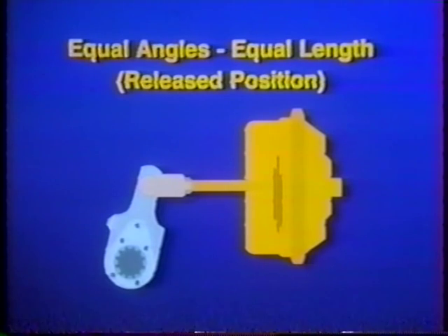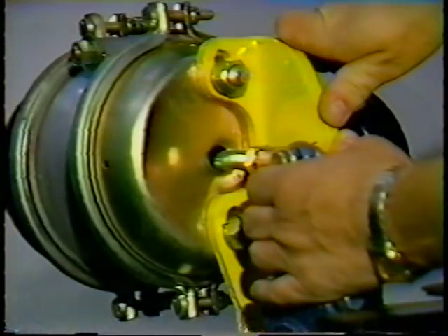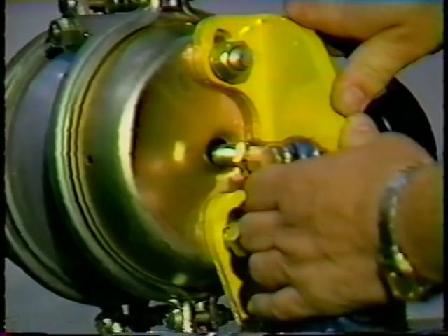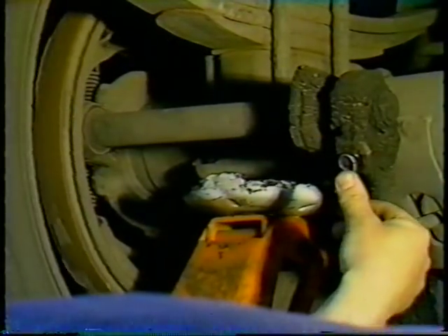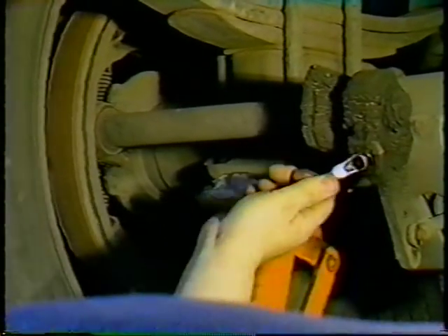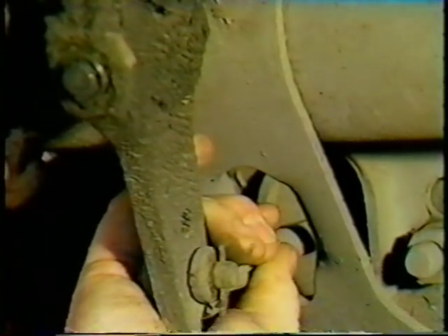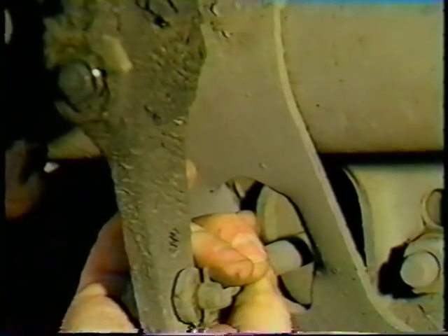The length of all push rods and the angle of the slack adjuster to the push rod should be equal on all axles. Only a half to 3/4 of an inch of free play should be possible when the linkage is moved by hand. Brakes should be adjusted so that push rod travel is as short as possible without the blocks dragging. This also limits flex in the system. Eliminating just 20/1000ths of an inch of extra drum-to-shoe clearance can reduce the required chamber stroke by 50% at 20 psi.